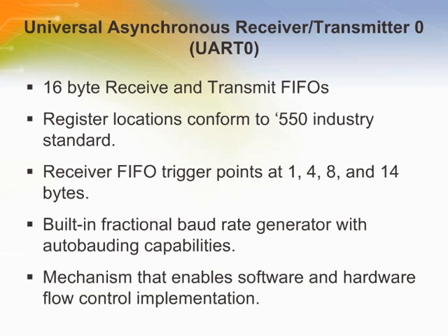After a valid character is assembled in the U0RSR, it is passed to the UART0 RX buffer register, FIFO, to await access by the CPU or host via the generic host interface. The UART0 transmitter block, U0TX, accepts data written by the CPU or host and buffers the data in the UART0 TX holding register FIFO, U0THR.